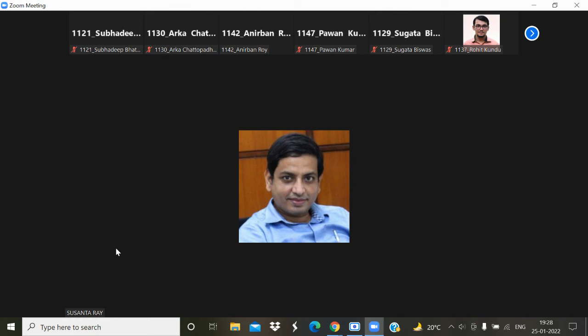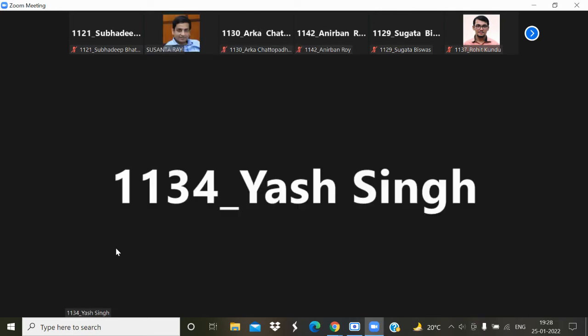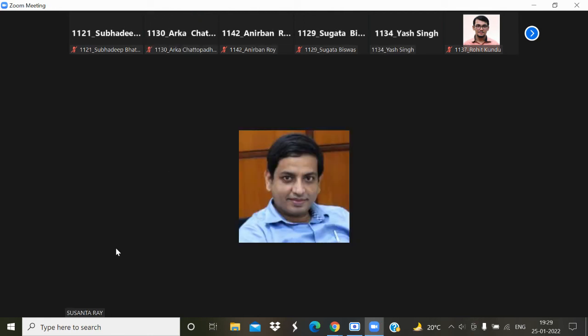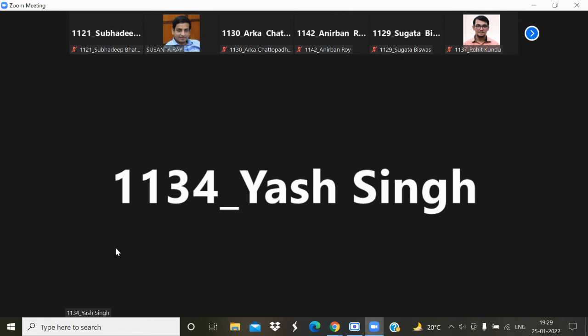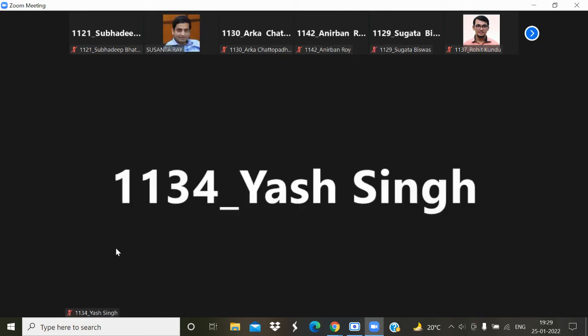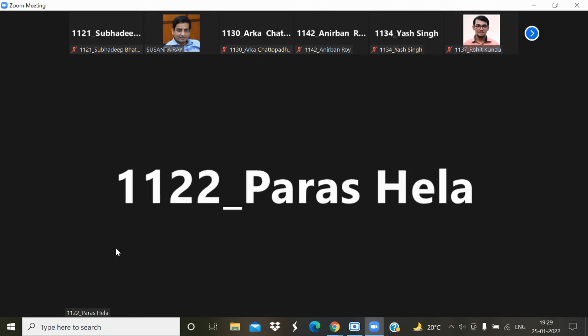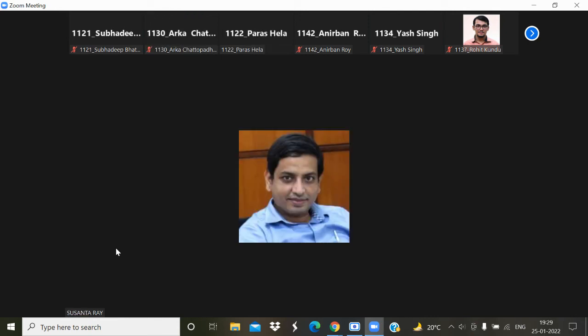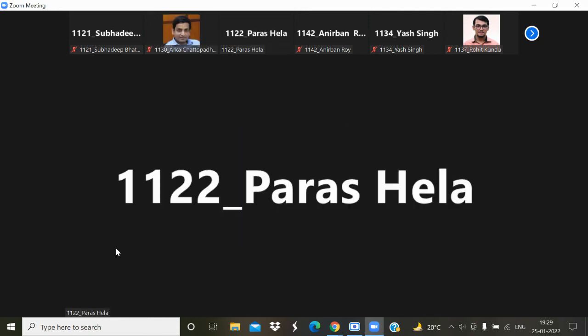Sir, for a 150 kilowatt machine, I have taken BAV value as 0.5 and my AC value as 30,000, and my C0 is coming out as 156.75, sir. So is it okay? It's okay. Sir, for a 60 kilowatt machine, I'm taking B average as 0.5 and AC as 25,000. So I'm getting C0 as 130.625. It's okay.